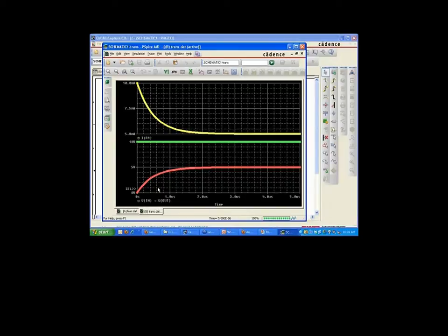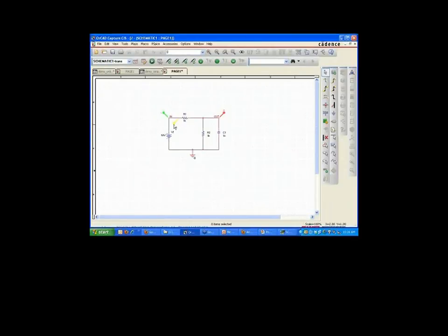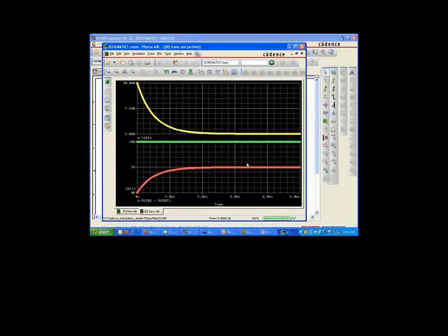And what I want to do is use a different input into this circuit instead of that DC source. So right now I have that 10-volt DC source, but I'd like to use some other waveform to drive my divider circuit here. So what I'm going to do, just for the case of simplicity, is use this red waveform, this output waveform, and take that waveform and drive it back into my circuit. I want to take exactly this waveform. So we've kind of seen already how we can pull that information out to a text file, and then we want to use that text file as a source.